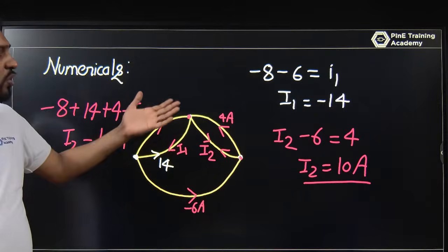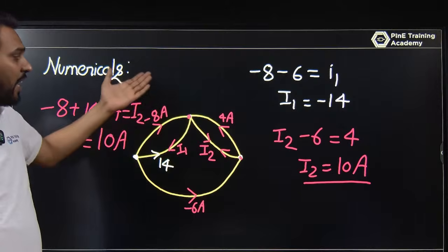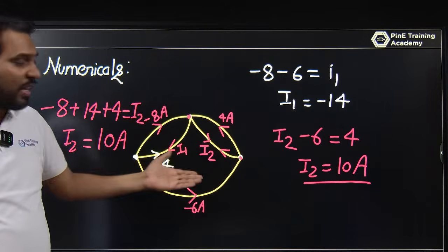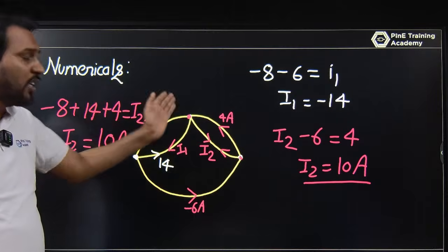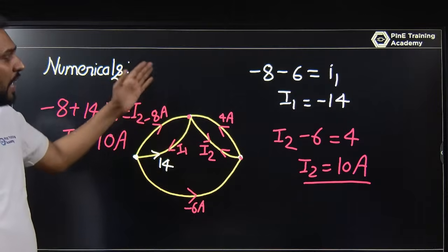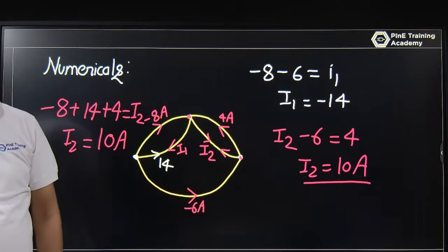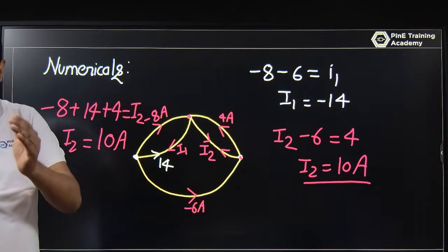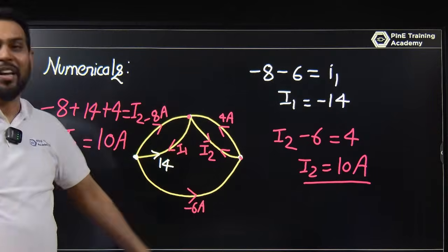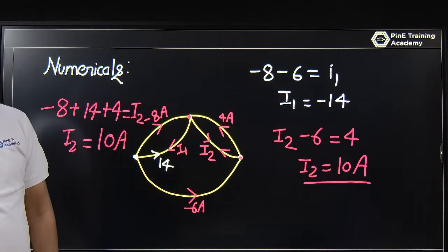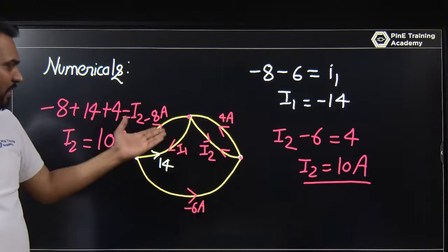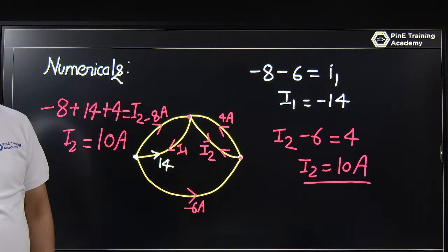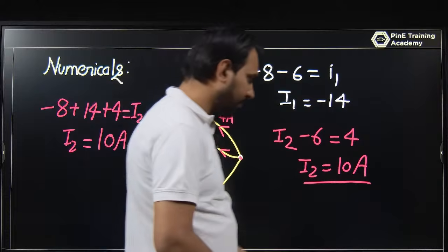If you solve some questions where the current is not feasible and the entering current is not equal to the leaving current, you can directly write that the circuit does not exist. But before that, just check it again. So this is the way you can analyze the circuit and the basic definition by the help of KCL.